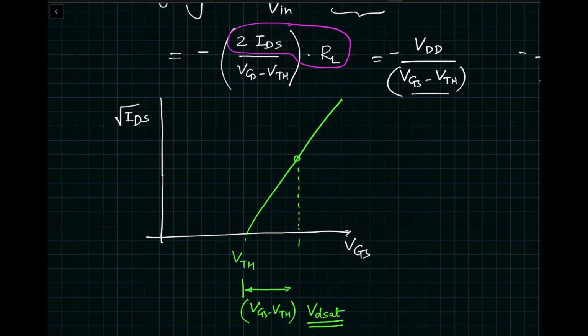And the trouble we get into is as we start reducing VGS minus VTH, you are actually traveling in this direction. As I explained earlier, this part of the curve right here is not as abrupt as I have shown it over here. In reality, you have something called subthreshold region operation happening over here, and we try to stay away from that region. So this is our subthreshold. So the practical value of VGS minus VTH or VD sat is every designer's choice. We can choose a number to be, let's say, 250 millivolts to keep it safely in saturation.